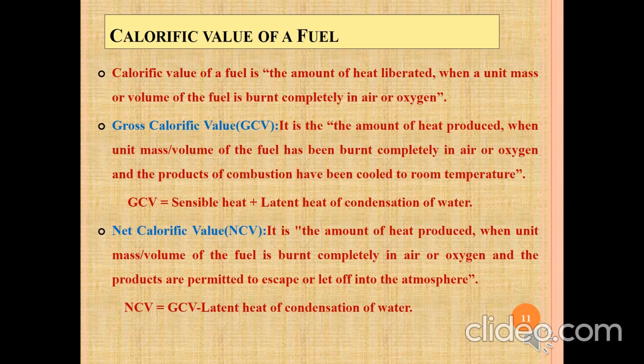That is, in gross calorific value, the products of combustion are not allowed to escape. The reaction is generally carried out in a closed container. So definitely one of the products is vapors of steam. So when you go to cooling, the vapors of steam condense back to give water. When it condenses back to give water, it liberates latent heat of condensation of water. So gross calorific value is nothing but the sum of sensible heat plus latent heat of condensation of water.